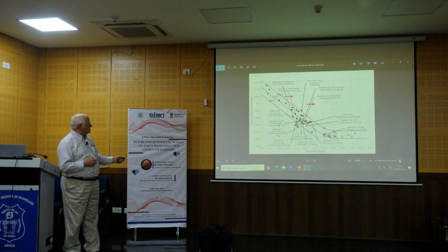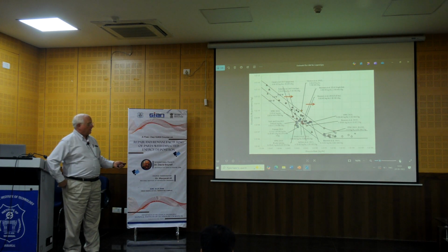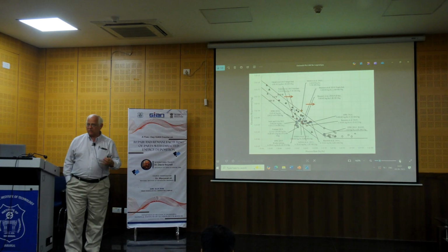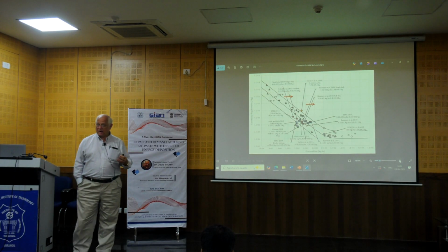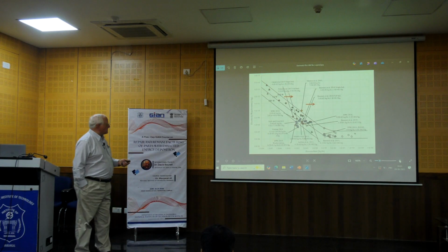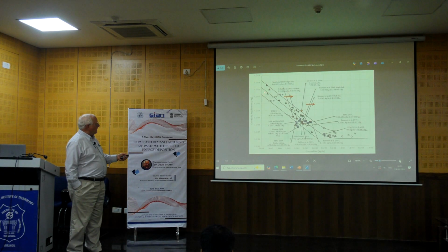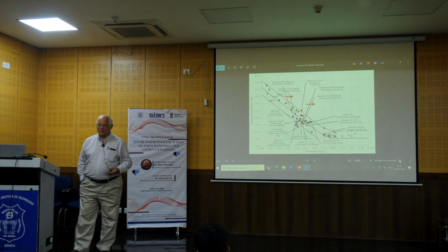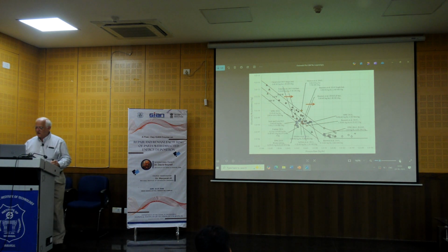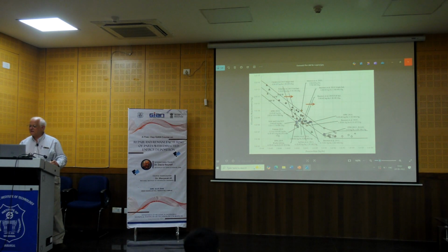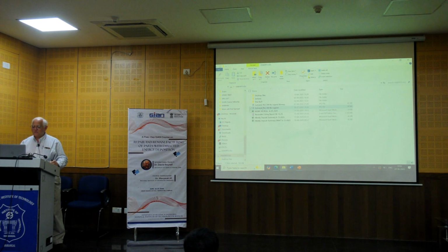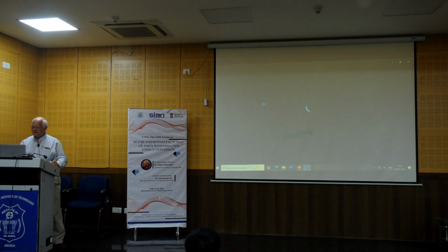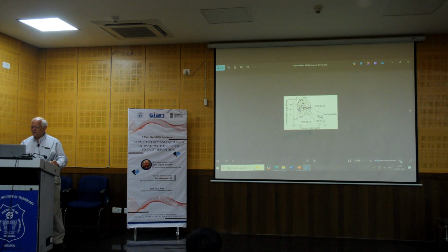So what's shown here is joules per kilogram, energy per unit mass, and the x-axis is the build rate, so many kilograms of material per hour. And what we see is that there's a reasonable correlation, and it's inverse, so that the faster we build, the lower the energy requirement. And if we concentrate on additive manufacturing, let me look at the other version. I think this shows the additive processes.